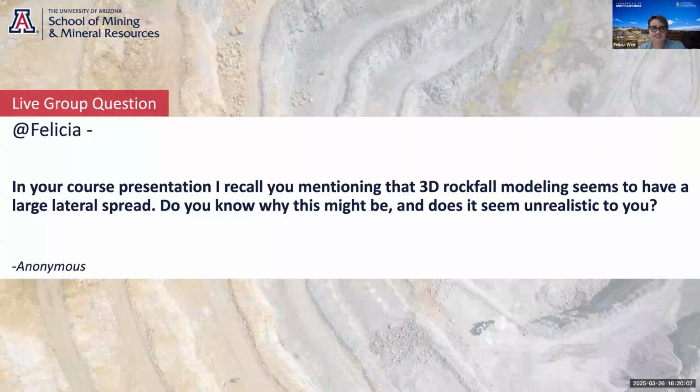Oh, good question. All right, so 3D rockfall modeling, I showed some examples of different software packages, and that they all showed quite a lateral spread compared to what the field trials had found. So instead of saying, is it unrealistic? I think what you've got to say is that it's low likelihood that they would actually spread as far as they had in that example.